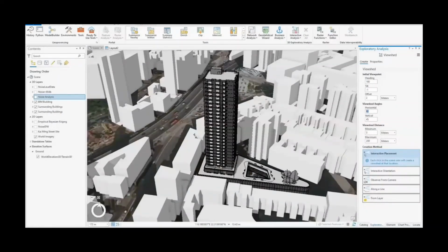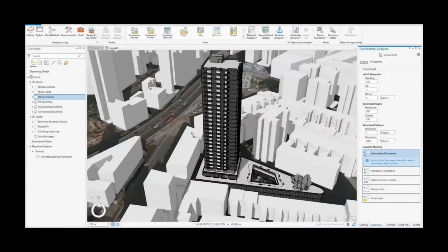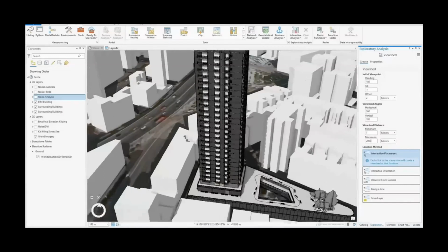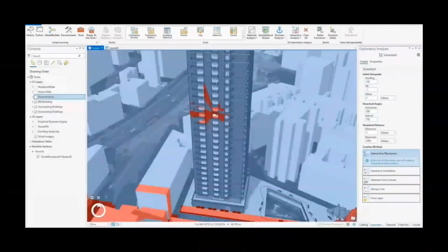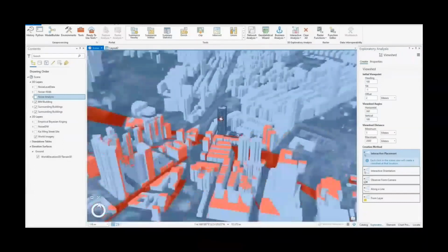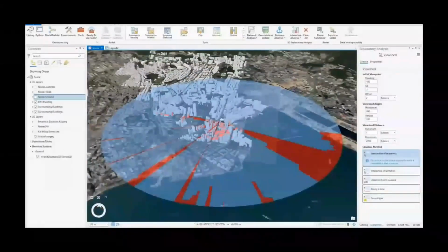So at the end of the analysis, we will have a comprehensive, all-round view of which parts are visible and not visible from the flats we would like to analyze. And finally, for the feature distance, we will pick 2,000 meters as the maximum, so that the system will analyze the radius up to 2,000 meters, as you may see here.